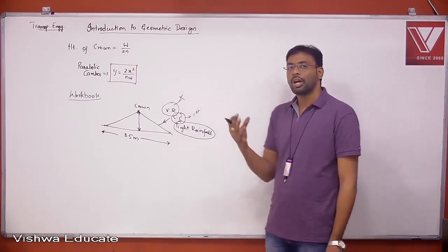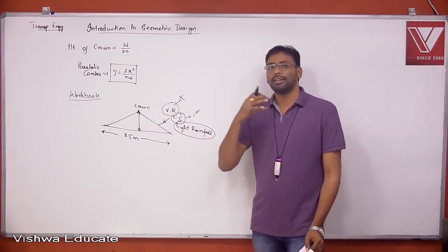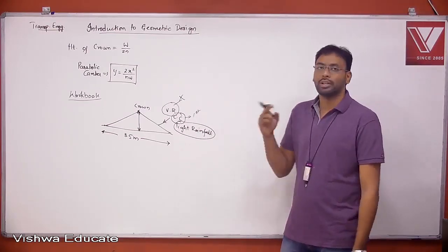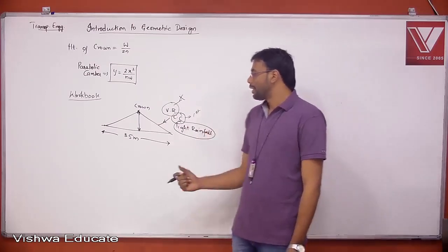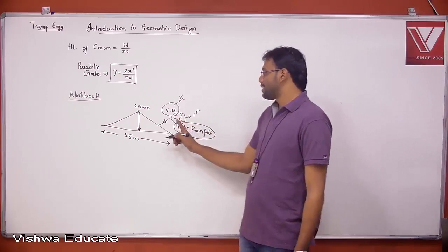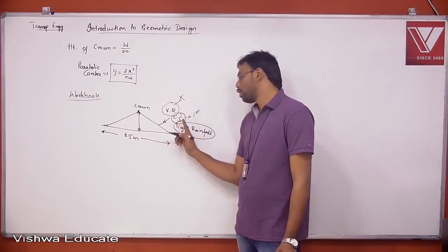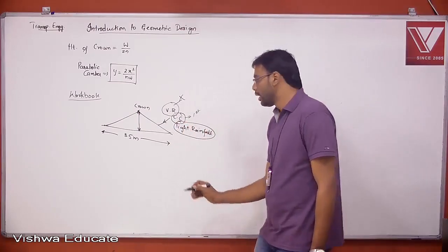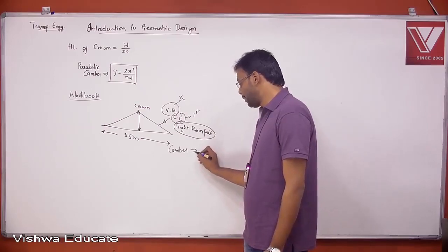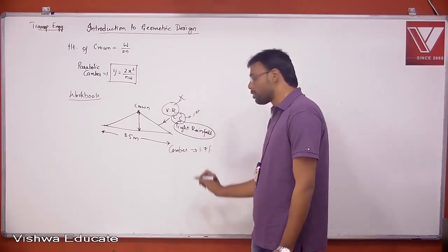So CC road is the first type, and light rainfall. Please look at the back pages of your notes, at the table given during the discussion, and tell me the value of camber to be considered. For a CC road of light rainfall region, the camber to be taken is how much? Tell me from the table. It is 1.7%, right?